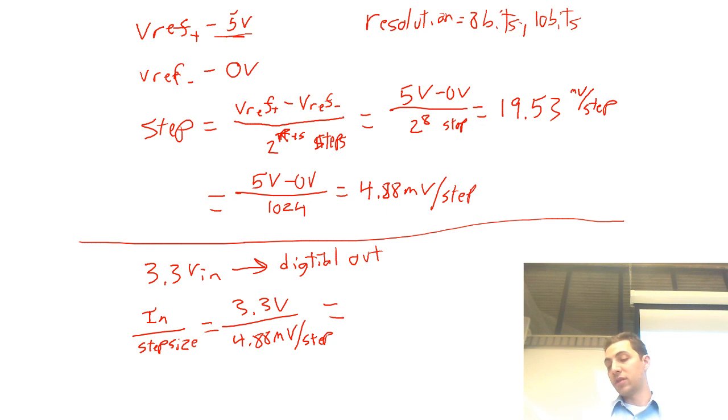That's 3.3 divided by 4.88 millivolts. Darn it. Millivolts per step. That gives me 676.23 steps.